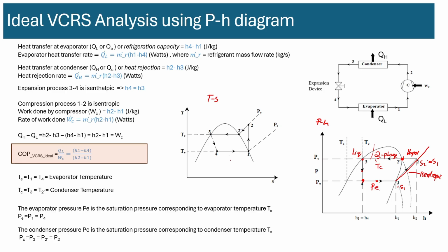So that pressure remains constant throughout, and the temperature remains constant inside the dome. Okay, and the liquid-vapor mixture becomes less liquid and more vapor. And finally, when we reach 1, it's all vapor. And vapor goes into the compressor, right? Isentropic compressor. There's no liquid going to the compressor. So as the vapor reaches 1, we finish the end of the evaporator, and it's going into the inside of the compressor. And the cycle repeats. Okay.